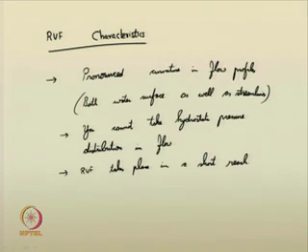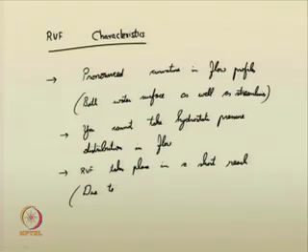If you recall the gradually varied flow, we suggested that the gradually varied flow phenomenon occurs in a large reach, maybe up to 2 kilometers, 3 kilometers. We had done some examples on that. But rapidly varied flow occurs within a short reach, within say 1 meter, 2 meters. So, what is the significance of this short reach? Due to short reach, your control volume for analyzing rapidly varied flow will also have a small length.